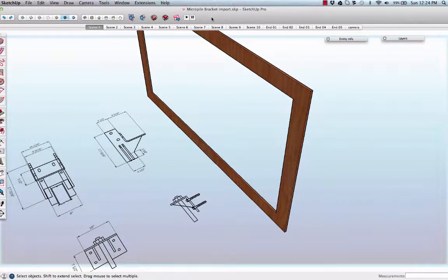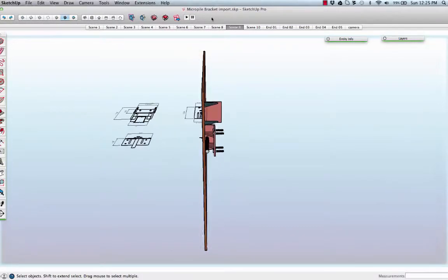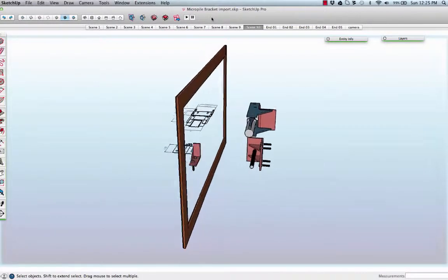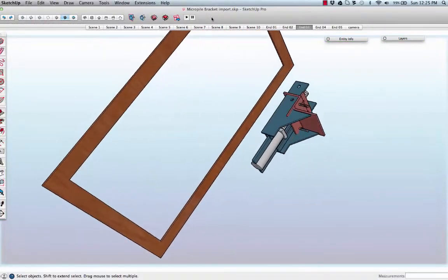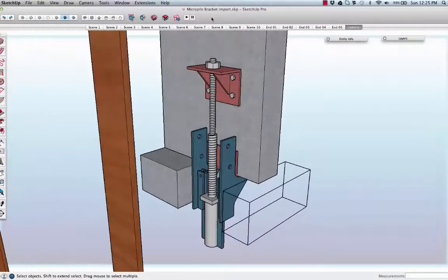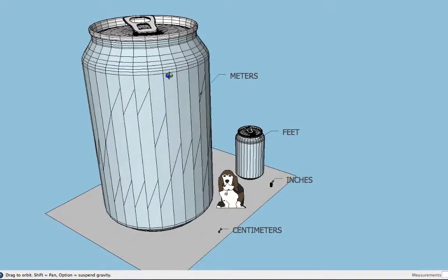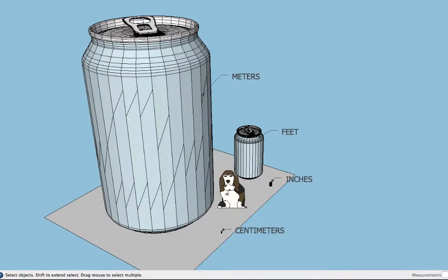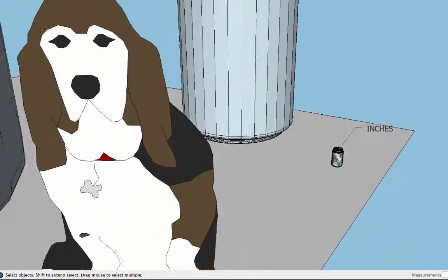Many building product manufacturers want to reuse their existing CAD models and turn them into SketchUp components. You must know the scale of the source file when importing it into another system to translate the geometry from one system to another. This means that the same object geometry, here a soda can, imported using different units results in very different sized objects.